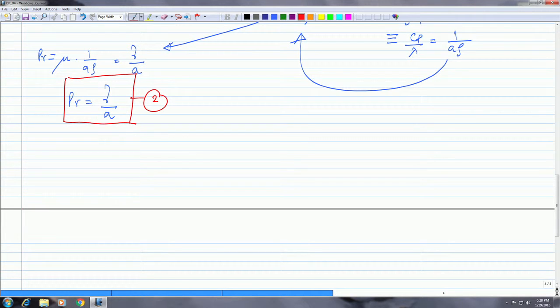Now, what we can infer from 2 is that it's a ratio of transport properties of a fluid with respect to momentum, right? Because there is a momentum change across the boundary layer due to the existence of the kinematic viscosity, to that due to the existence of heat transfer, which is A here, thermal diffusivity.